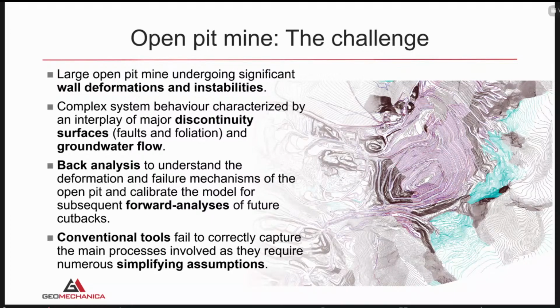We had to back analyze it initially to understand what was causing the deformation and failure, so understanding the deformation and failure mechanisms of the open pit and calibrating the models for subsequent forward analysis of future cutbacks. So we not only had to back analyze, we had to provide predictions of what will happen in the following stages of the mine design.